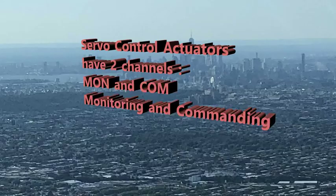So here in the Airbus A350, we have this configuration. Remember what I said about the servo control actuators having 2 channels, because it has to have a channel for monitoring, which is going to be receiving feedback signals from the actuators back to the computers. So there are 2 channels, just like in other aircraft.